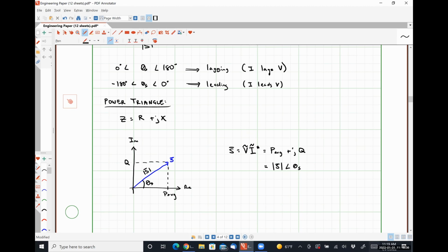All wires are rated for their ampacity, and the ampacity values are related to the apparent power, okay? So the wires that are connecting the receptacles here in this room, let's say it's on a 15 amp circuit,